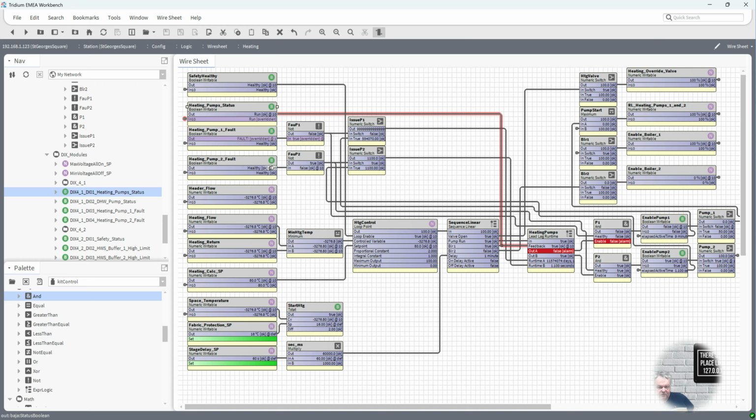And if we was to do a start, so if I was to take off that in, so we stop it all, so none of them are running, I'm expecting pump B to start immediately once we actually do that, and pump B starts. Let's clear out the alarm just to show you that it wasn't just a fluke.